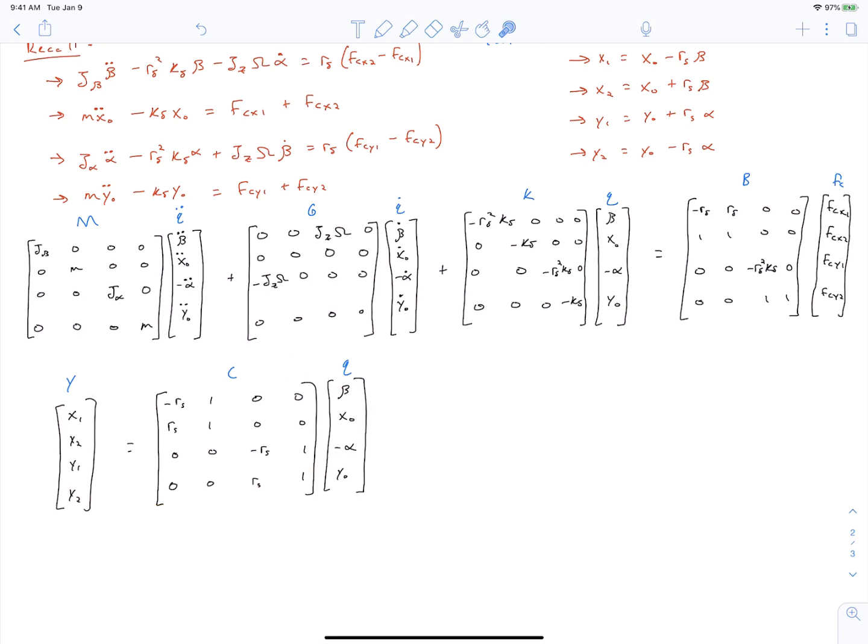So this represents a canonical form, like I was saying, and you can use these matrices. You can study the form and shape of these matrices and properties of these matrices to understand things like the stability of the system, the observability of the system. There's a rich body of controls and linear and system theory literature out there that will help you design controllers to act on this system and to study this system. And this is the standard format that you will see magnetic bearing papers published in when they're discussing the control of a centralized implementation, a centralized control implementation.